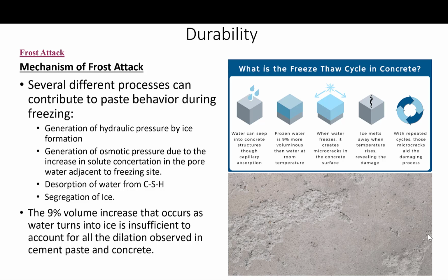The formation of ice lenses, as this phenomenon is called, occurs in soils, and it is responsible for the frost heave in soils. The development of ice lenses in concrete requires the presence of large voids, which could be micro cracks or voids occurring under reinforcement or large aggregate particles, due to segregation or poor compaction. An external supply of water that can readily migrate to these voids is also needed in this case. So these are the possible explanations for the cause of why the pressure develops and cracking occurs due to freezing.